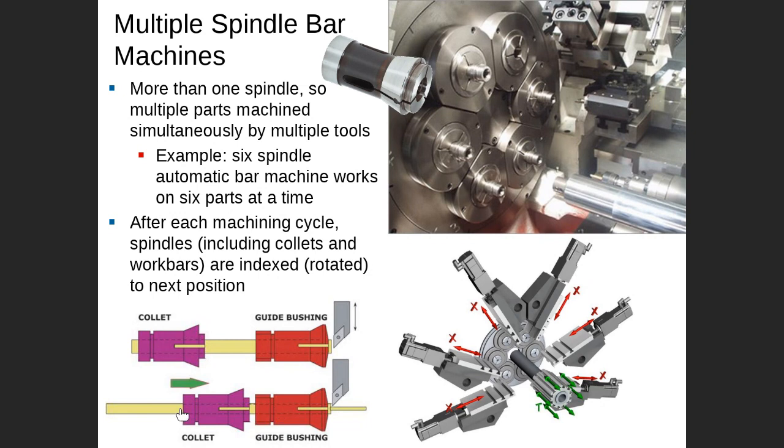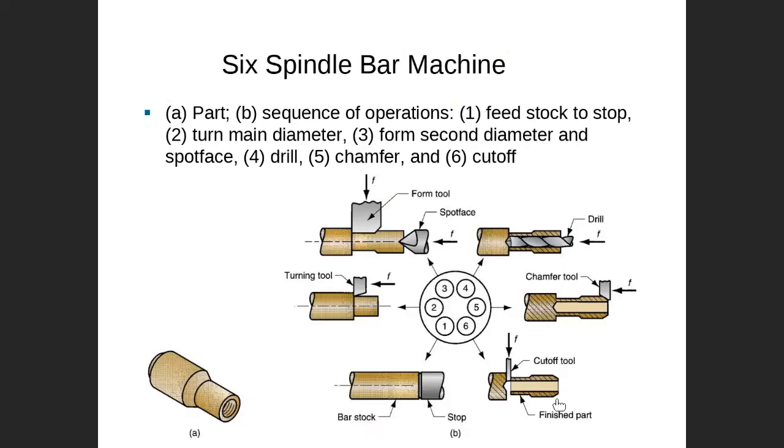To feed the workpiece, we push like this to open and feed the workpiece, and then we bring it back to clamp and then it is used in a cut. And here we have several tools corresponding. Every bar, we call it bar here, has one tool located at every bar to do a certain cut. How does it actually work? It works like this.